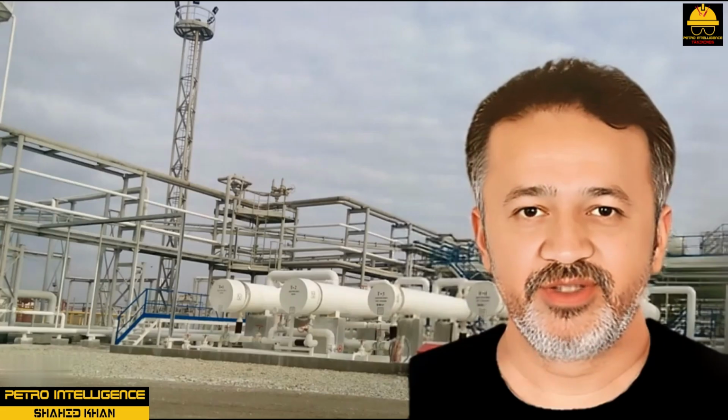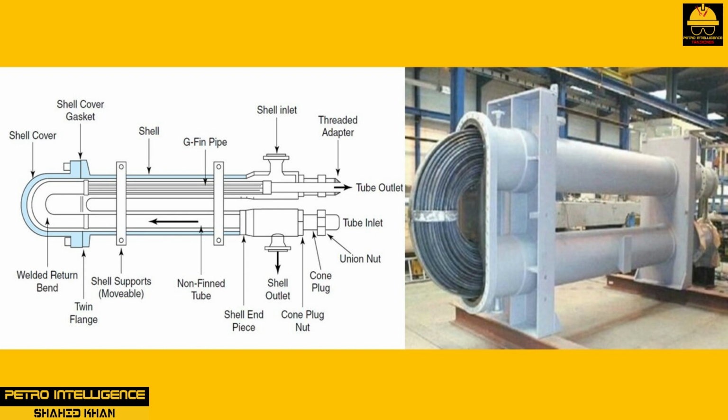Hairpin heat exchangers. The chemical processing industry commonly uses hairpin heat exchangers as shown in picture. Hairpin exchangers use two basic modes, double pipe and multi-pipe design. Hairpins are typically rated at 500 psig shell side and 5000 psig tube side. The exchanger takes its name from its unusual hairpin shape.